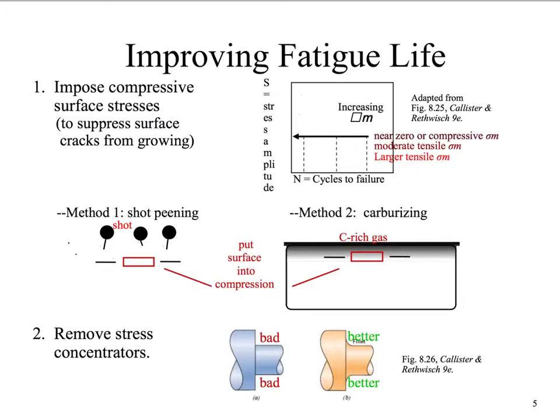Some things that can improve the resistance to fatigue of a metal alloy involve improving the surface by finishing it with polish, also reducing the number of internal defects, eliminating sharp surface discontinuities, and lastly, case hardening.